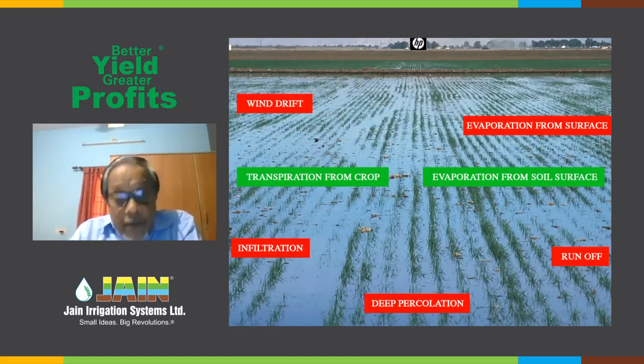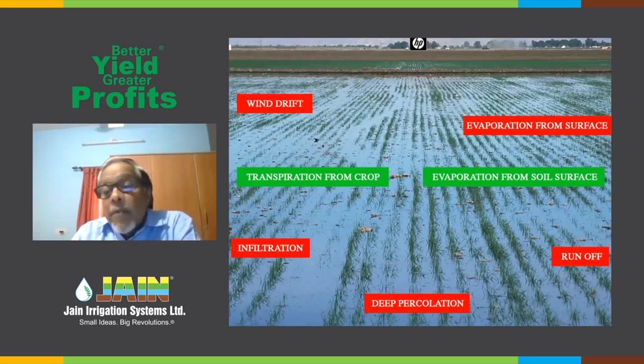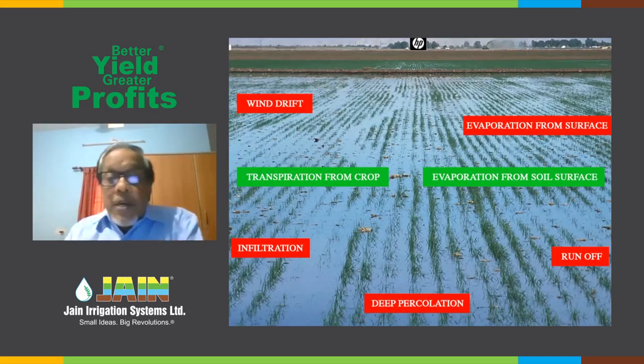And then we have infiltration, which goes down, and the deep percolation. Depending upon the soil strata, the lower soil strata, water can go down into the soil profile. And sometimes laterally from one end of the field to the other or to the next field, we get runoff. That is physical water actually flowing above ground of the soil and then moving to a place where you don't want it to go. And then evaporation from the surface I mentioned already.